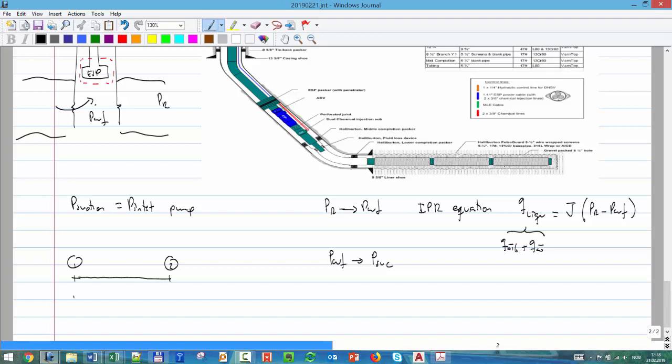What it says is that H1 will be equal to H2, the energy. You have this head, and the energy is basically P1 divided by rho1 g plus v1 squared over 2g plus what other kind of energy do we have? Z1, which will be equal to P2... Yeah, the density is the same. You remember that equation, right?